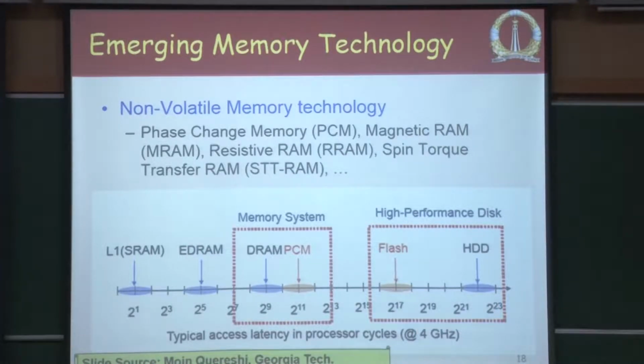Okay. And then of course, we have this PCM, which is the phase change memory, whose read access time is somewhat similar to the DRAM access time, but its write access time is a little bit more, right. It is non-volatile, but its durability is limited, right. You can only do a certain number of reads and writes on that memory, after which the device fails. Okay. So that's one other aspect of phase change memory or some of these non-volatile memories.